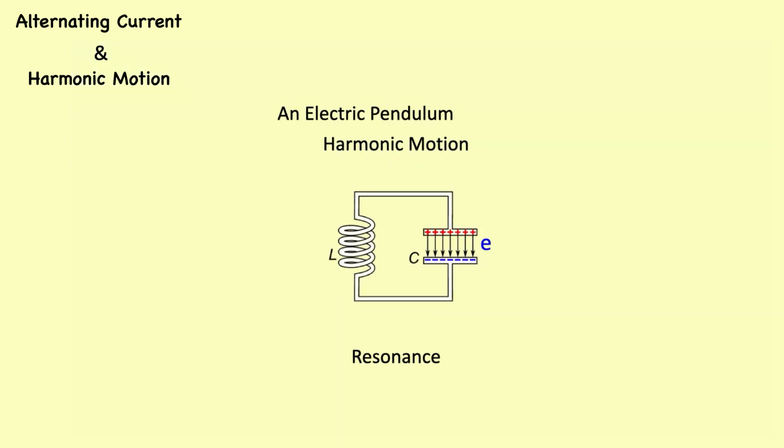The same is true for the capacitor inductor circuit. The rate of oscillation is strictly dependent on the size of the capacitor and inductor, not on the amount of the voltage or the current at each respective peak in the waves. The ability for such a circuit to store energy in the form of oscillating voltage and current has earned it the name a tank circuit. Its property of maintaining a single natural frequency regardless of how much or how little energy is actually being stored in it gives it a special significance in electric circuit design.